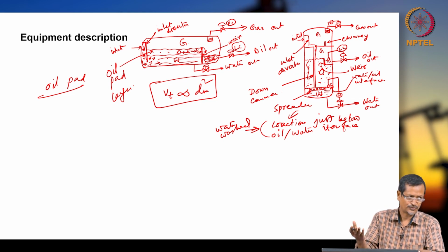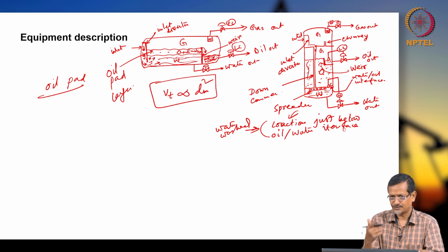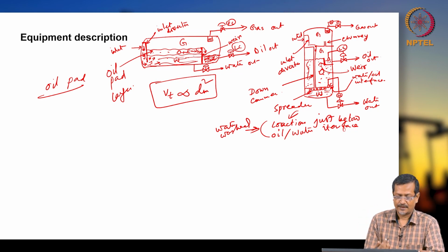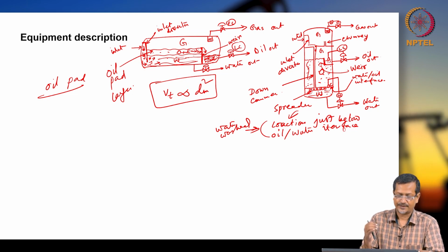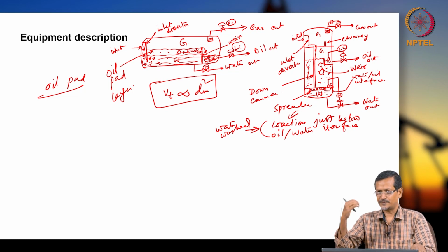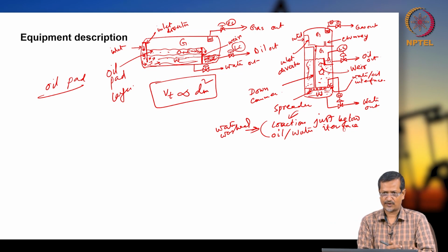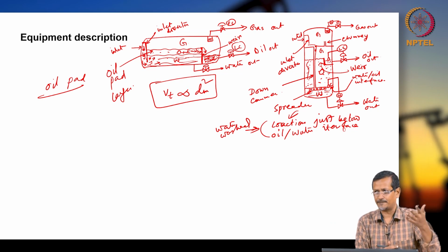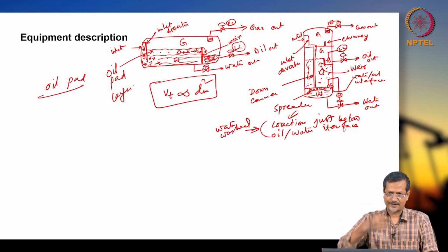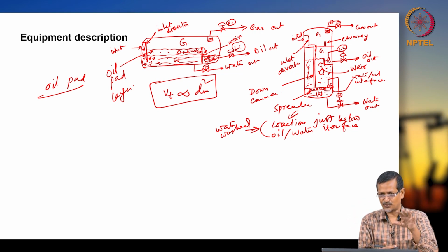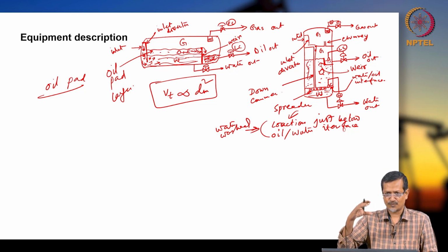not show. Gradually we will show, like a wave breaker, and a vortex plate so that the vortex will be broken. There will be a splash breaker. So with some mechanical arrangement, the splashing will not be created; rather it will create laminar, smooth flow, so that water and oil will get separated and will not mix up again. But if you create too much turbulence inside the separator, what will happen? The water and oil particles will try to mix up again. So you try to create a laminar or calm zone. Actually in a vertical separator you are creating more calm zone.